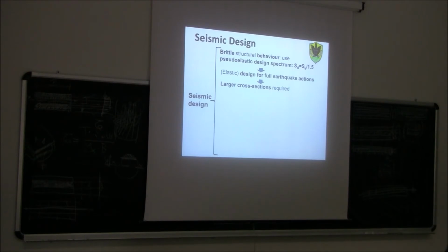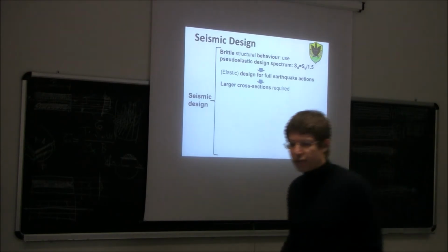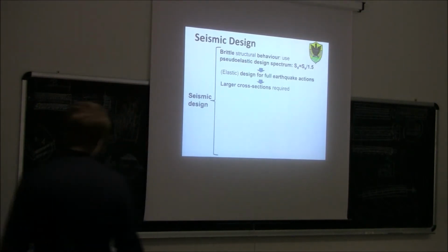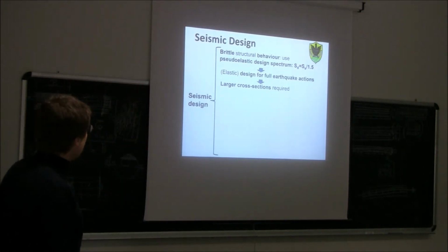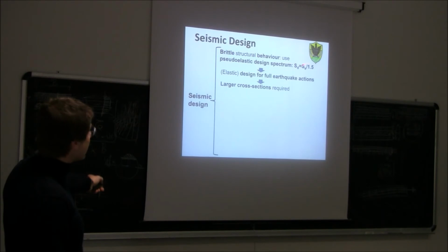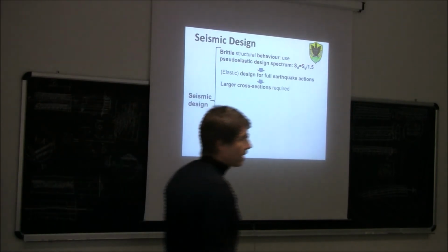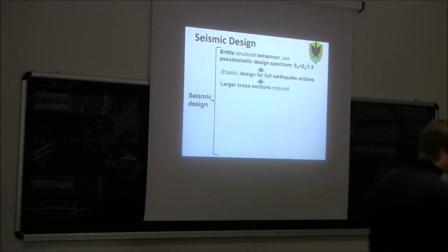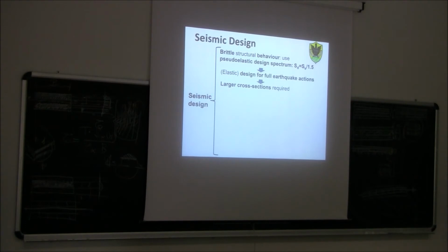If I have a brittle structure, a structure that cannot dissipate energy, then I need to use the pseudo-elastic design spectrum, the same that you're going to use for your project. For your project, you assume that your structure is brittle, even if it is not, so it doesn't have any capacity to dissipate energy, meaning that you have to take the full elastic forces into consideration.